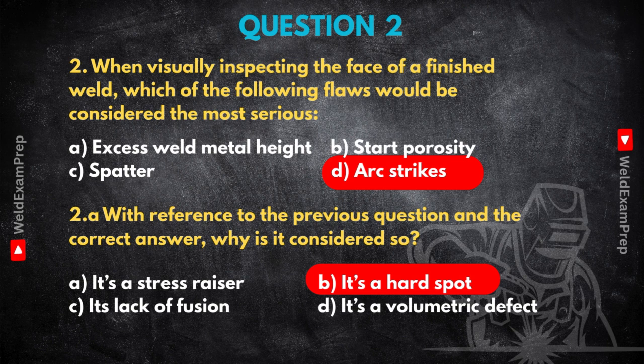An uncontrolled quench, basically. Now, for many steels, especially carbon and low alloy steels, this super fast cooling doesn't let the metal form its normal, tough structure. Instead, it forces it to transform into something else. Often, it's martensite. Martensite, I've heard of that. Very hard. Extremely hard, but also very brittle. Low ductility, low toughness. Think of glass versus plastic. Martensite is more like the glass.